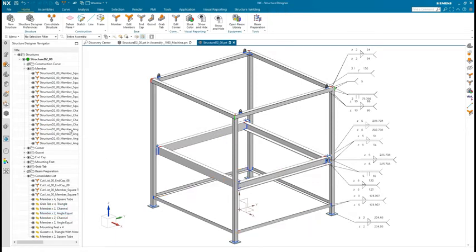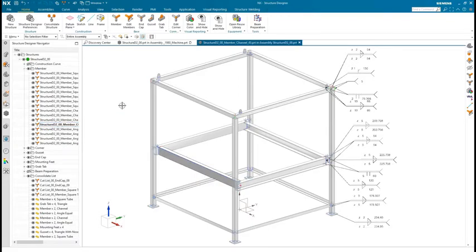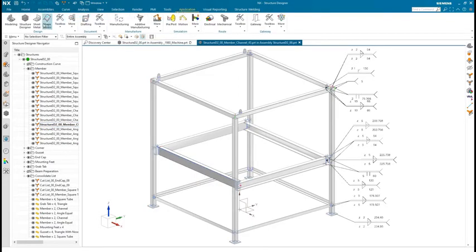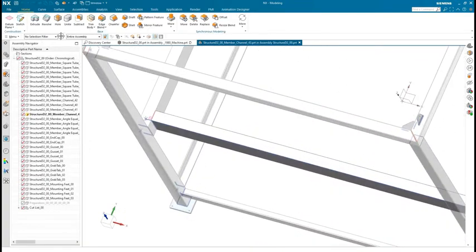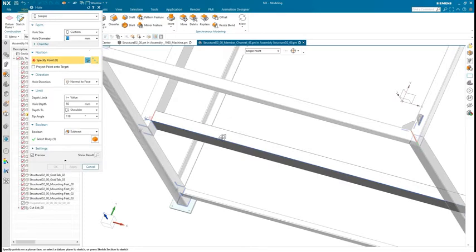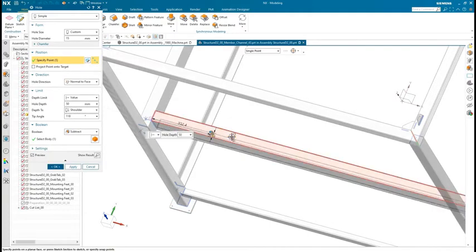If any last-minute changes are needed, make an edit and repeat the process. For example, let's add some mounting holes to the member that was part of the consolidated group. Here, we'll enter modeling and punch a few holes in the upper flange. So we can focus on the consolidation process, we'll skip the process of placing holes in an exact location.